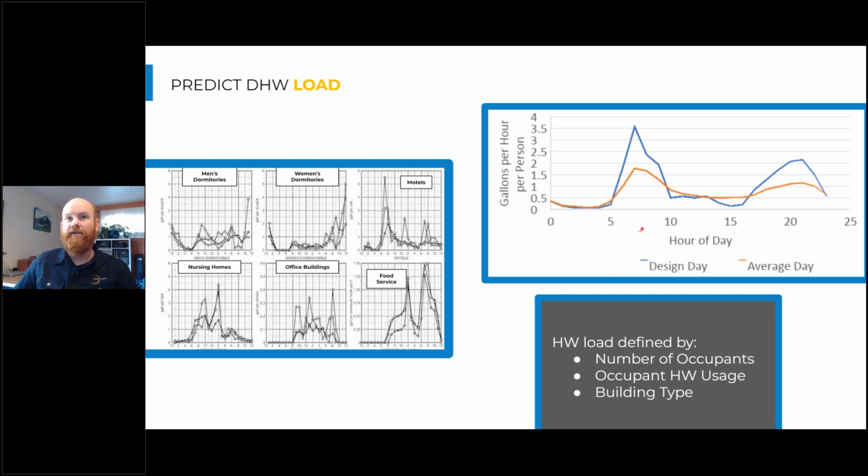We can do that with the heat pump water heating system, but it just adds unnecessary cost to the project. And so I really encourage you to evaluate when you need to have recovered that system by. That might be a 6 hour period instead of a 3 hour period that you're more used to working with. But essentially, we need to be able to maintain hot water during these two big load profiles. And typically we do that by storing water in a storage tank before this load happens, so that we're fully charged before people start using water in the morning. But it's really important to understand when those loads are.